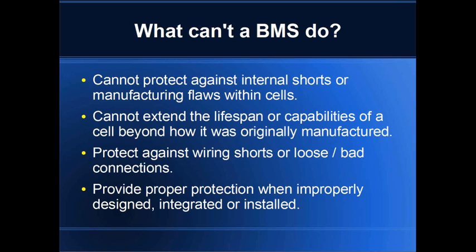While it can offer some protection against shorts outside of the battery pack, if you have an on-off switch for your battery, or a contactor, or some type of device that can shut off power from going in and out of the battery, it can protect to some degree against shorts there. Whatever the switch is has to be able to handle the fault current and to be able to handle switching the fault current. There also may be some timing related issues with that, so we always still recommend having fuses in there whenever possible, because that offers you better protection.